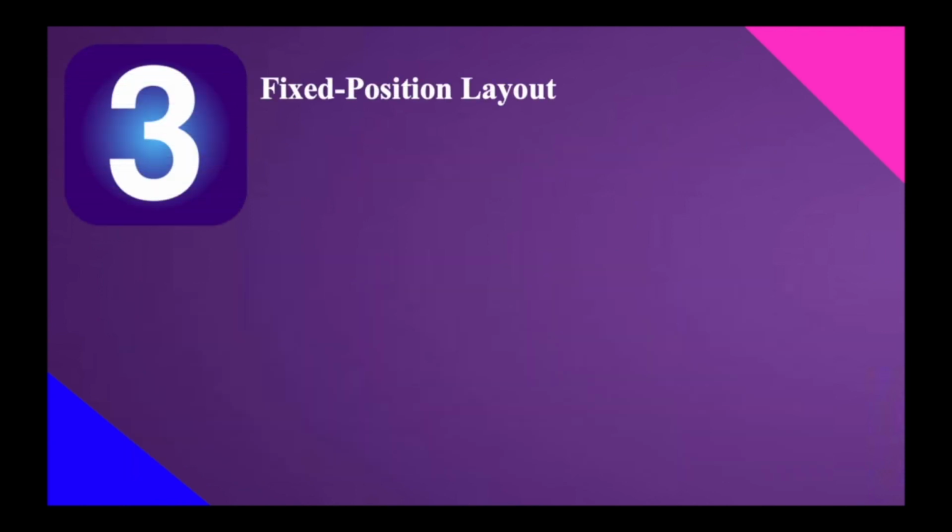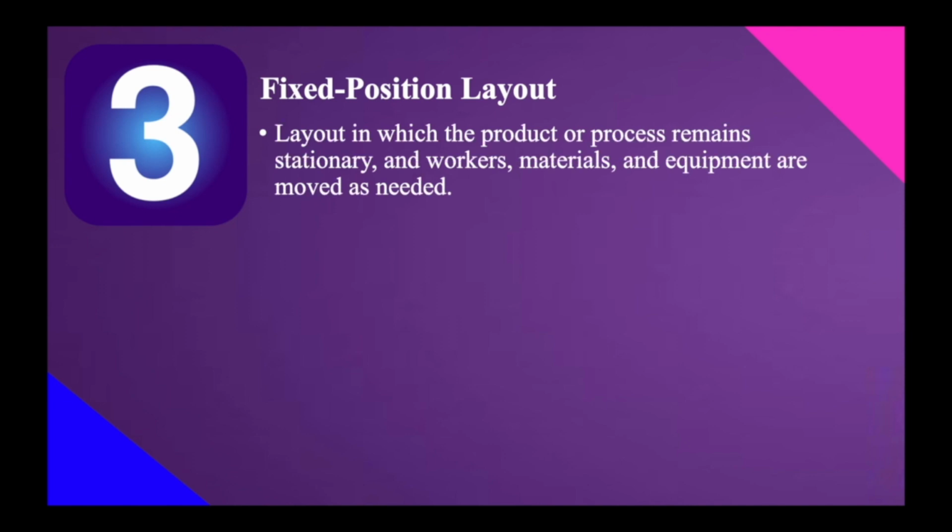Okay? And the third one is the fixed position layout. Guys, when we say fixed position layout, this is a layout in which the product or process remains stationary. When we say the term stationary, meaning hindi po gumagalaw. There is no movement. Nandoon lang yung ating ginagawang product or yung process natin. And workers, materials, and equipments are moved as needed. Yung workers yung nagmo-move, yung materials yung nagmo-move, yung equipment mismo yung nagmo-move papunta doon sa product natin. That is the reason why it is called fixed position layout.